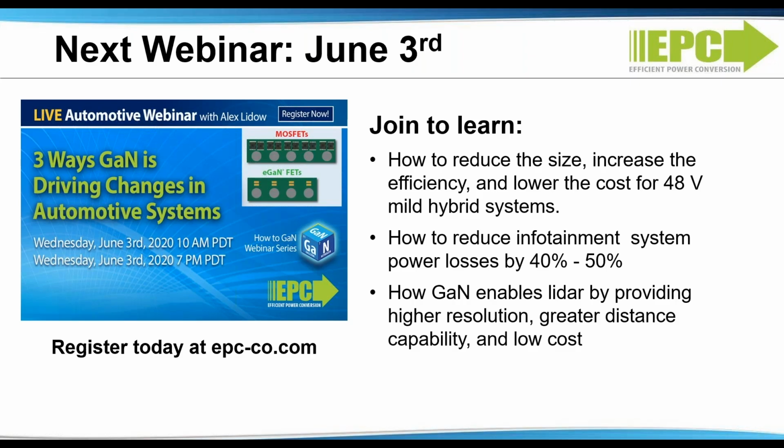So we've eliminated the primary source of EMI. Now, a lot of questions come up about the faster switching speed. Doesn't that increase your EMI? What happens is, the faster the switching speed, first of all, the lower the energy you have in the switching transition. But secondly, the Fourier transform of that switching transition is out at higher frequencies, which typically requires smaller filters and less expensive filters.